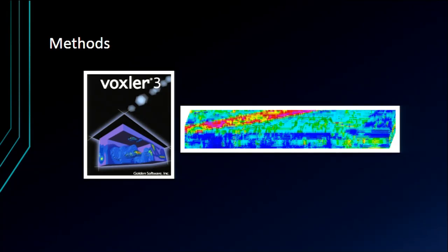So then we took it, and since it comes out as sort of an analog wave, you can cut slices of it and make either a profile view of it or a flat surface view of it, like a plan view. But what we wanted to do, since we were going to bring in some LiDAR, terrestrial LiDAR, is turn it into a point cloud.